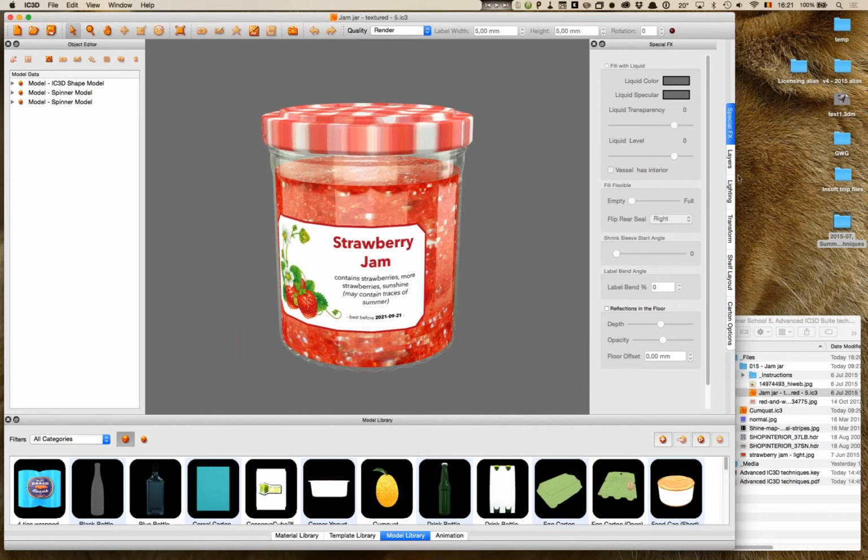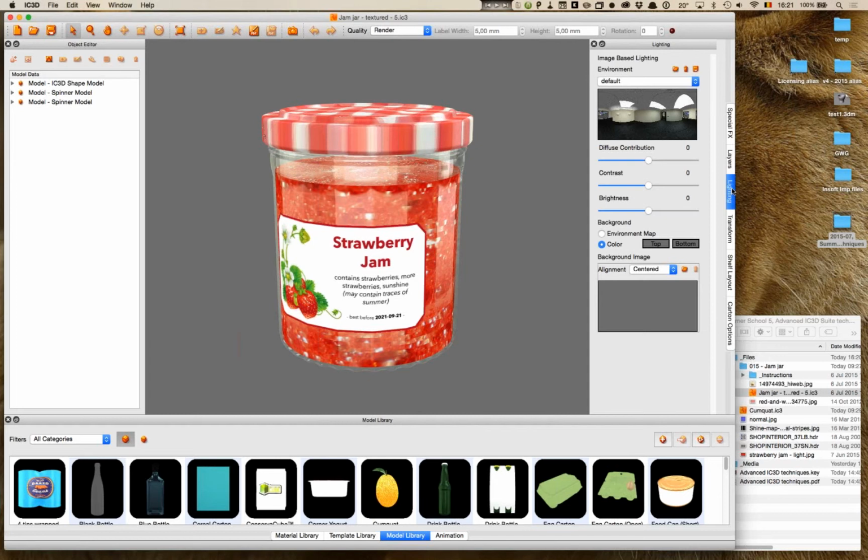And all of the lighting stuff in iC3D Suite is contained in a tab called Lighting. That makes sense, right? And what you have there is this little pop-up menu, and that contains all of the lighting environments that you have in iC3D Suite itself. When you install the application, there will be 3 or 4. Some of these abstract ones are in there. And then you can use the controls that you have here to import such a lighting environment. You can also export them.